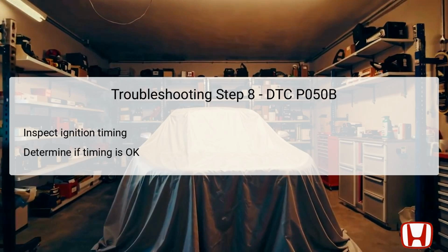Proper ignition timing is critical for optimal engine performance, especially during cold starts. Using the HDS, assess whether the ignition timing is within the specified range for proper function. If the ignition timing is found to be accurate, the diagnostic process continues on to subsequent steps. However, if the timing is incorrect, further investigation is necessary to ascertain the source of the malfunction.